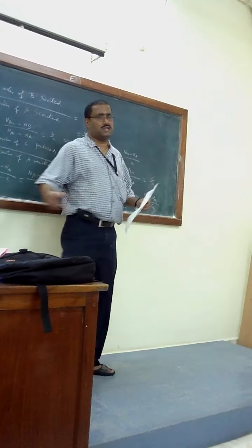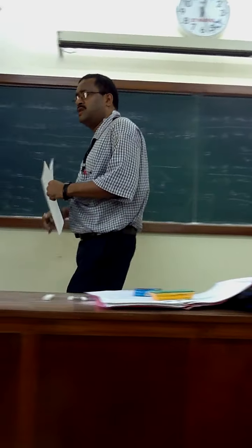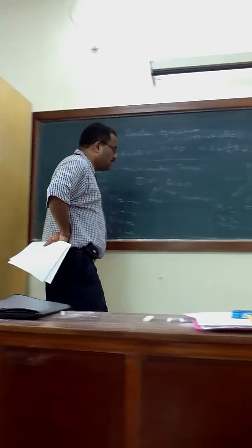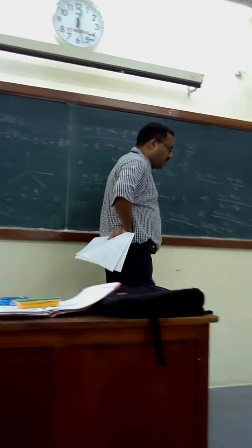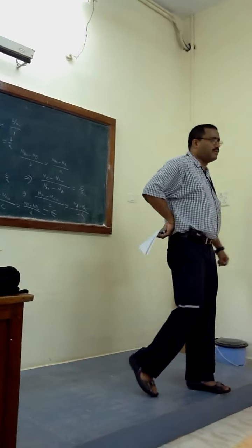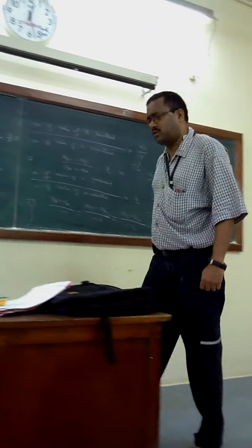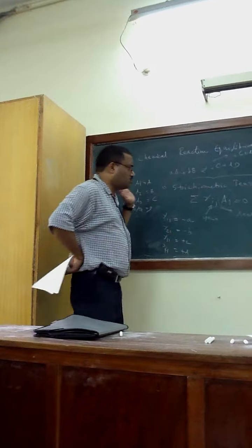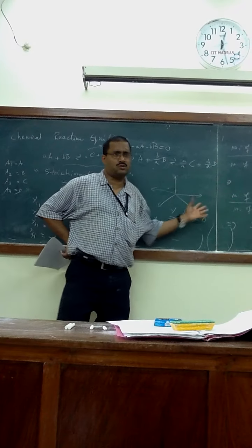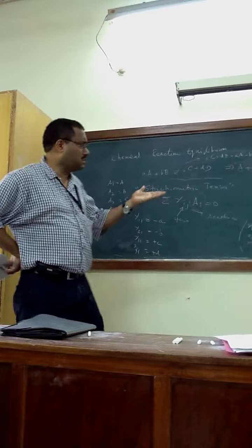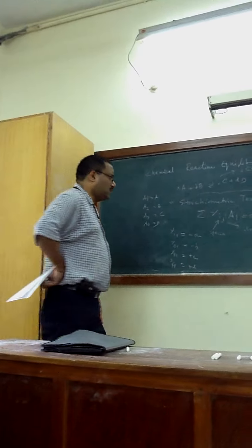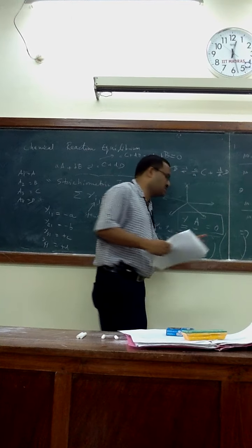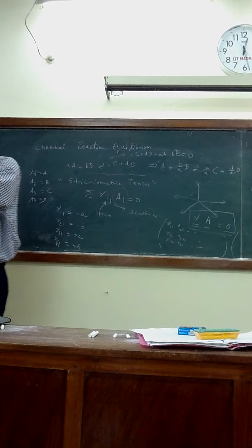So then do the row echelon form here, and in the echelon form we can easily find out how many non-zero rows there are. The rank of the matrix is defined as the number of non-zero rows in the row echelon form, and the number of non-zero rows will tell you how many independent chemical reactions there are. So that's why it is better to have this type of format. The world of chemical reaction engineering can be represented by this equation.